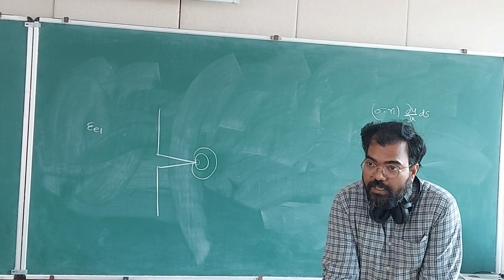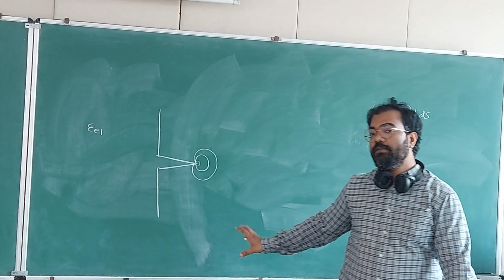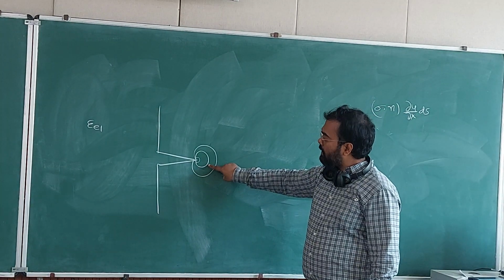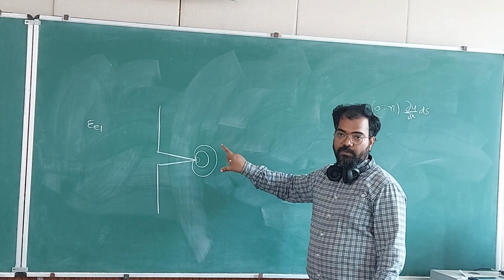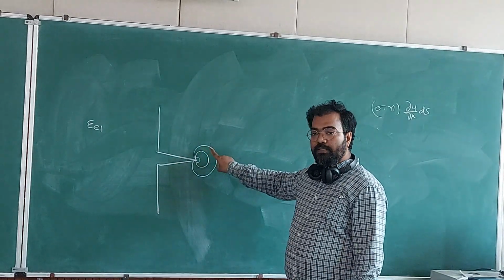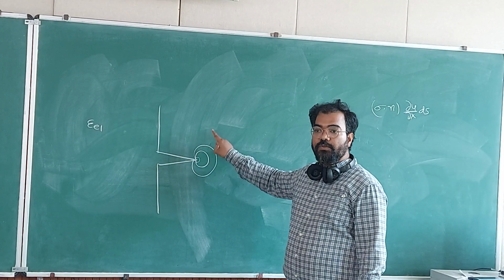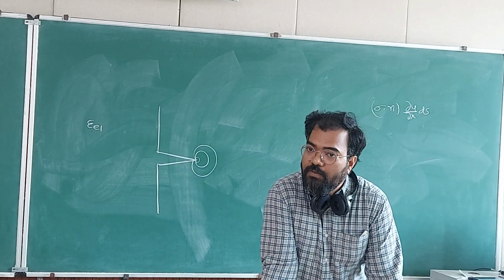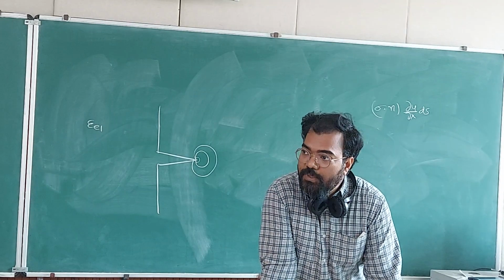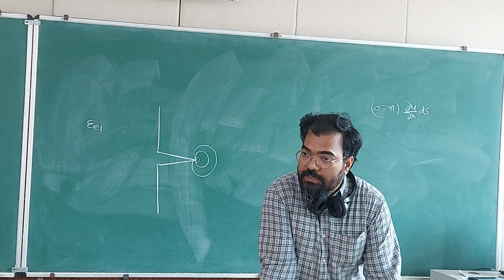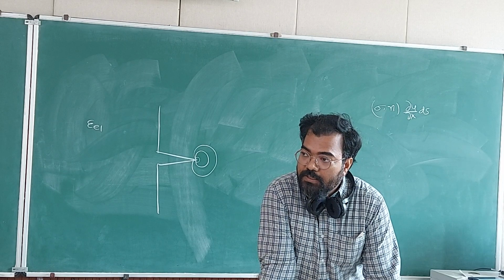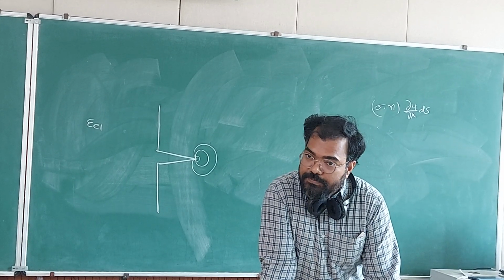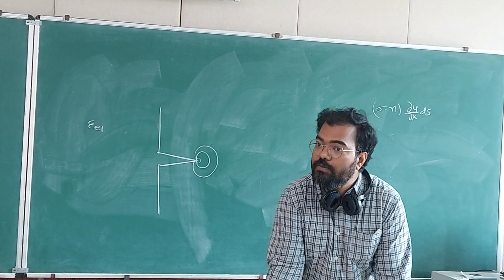So if you load that sample and stop the test in between, when you expect that the creep zone is larger than the plastic zone, and then you take hardness in this area, you will see two different regions with two different hardnesses, because they are deformed to different levels. One zone is deformed because of plastic deformation, which is time independent, and another is deformed where a little bit of relaxation has happened. So it is a little bit softer. Okay, it follows a different equation.